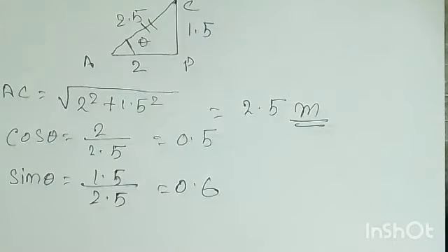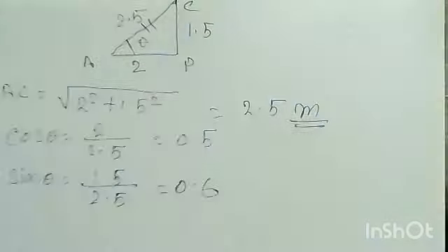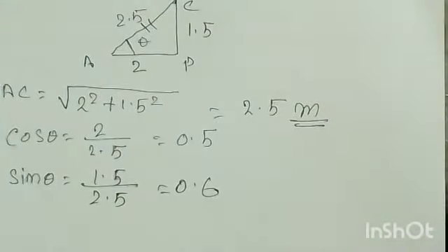Now everything is over, that we calculated the vertical and horizontal reaction at each end, and we also calculated the angle with which the members are inclined. Now we need to take the joint and then find out the forces in each member. One by one we'll choose the joint. Always remember that you start the calculation from the end joint, right? That will be better, specifically where you'll get one of the forces.